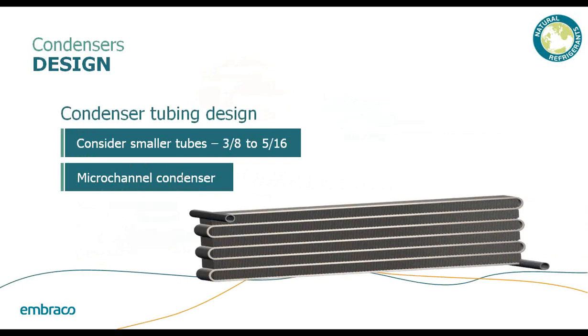Some things to help with the condenser size. If you're finding that you're not able to achieve the charge with a 3/8 inch tubing, consider using 5/16 inch tubing as well. Also, microchannel condensers are a good way to reduce charge dramatically. Again, there is going to be a cost impact with going to microchannel condensers. But if you really need to meet the charge, it's a good way of getting there.